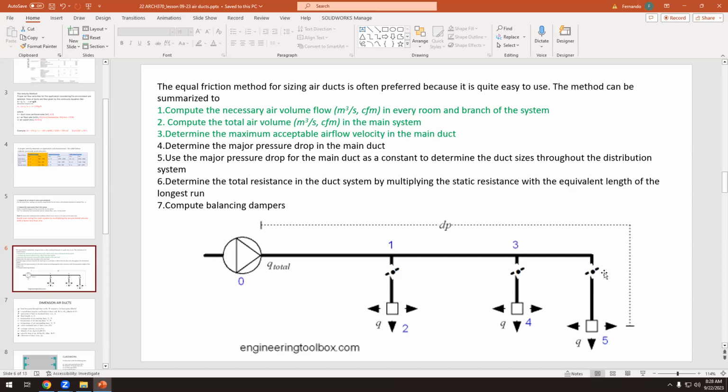Before giving the owner the keys to the building, someone has to check this, and they have to check the hydraulic circuits, the hot water, the heating, whatever, and they have to check the air ducts. It's not just, okay, I have made all my calculations and everything is correct. It's correct, but now you have to adjust all these valves, and people usually don't do it.